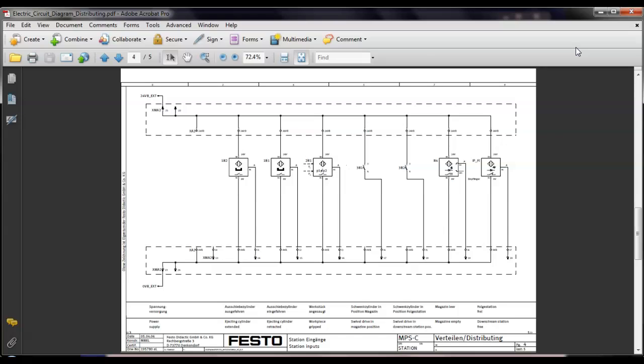Now down on the outputs, those are relays. Relay contacts don't care. If you look at the outputs of the PLC, all they say is AC DC. So on this PLC I could set up a contact here as sourcing, the one next to it as sinking, and the one next to that as AC. That's the big advantage of a relay output, is that you determine whether you want sinking or sourcing or AC or DC.